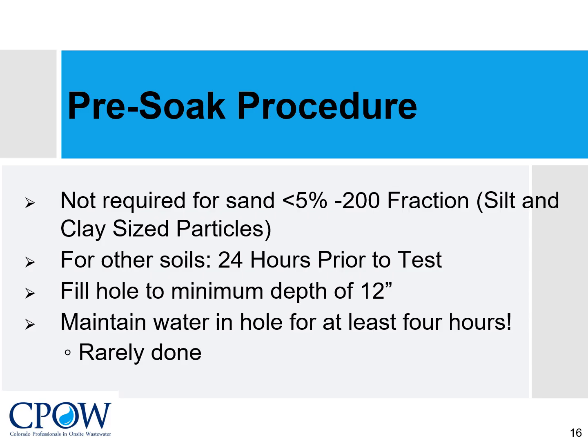After preparing the holes, you will want to load the holes with water. Pre-soaking the holes is required unless the soil is sand with less than 5% minus 200 fraction, which is silt and clay particles. For all other soil, you want 24 hours prior to the test of soaking those holes. Fill the hole to a minimum depth of 12 inches and maintain water in the hole for at least 4 hours. This is rarely done, which is where we see inconsistencies with the percolation results.